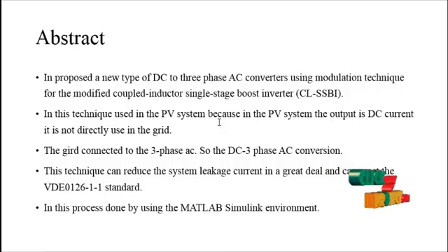The 3-phase inverter is controlled based on pulses. We use sinusoidal pulse width modulation to control the overall inverter system. In the grid we consider different loads with different active power and reactive power, and then finally we measure the voltage of the grid, the leakage current and the output voltage level, and compare them to the VDE 0126-1-1 standard to check whether our output is accurate or not.